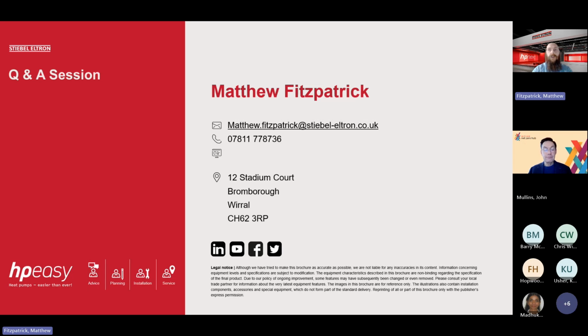So if you've got a gym, a sports arena that needs heating and cooling, and you've got the area, I would say go for ground source because that can use the energy from the ground to cool the buffer rather than using the heat pump. So that's offsetting the cooling costs. And then if it's an office that's well insulated, I would have heating and cooling seasonal rather than simultaneous, quite simply because the heat pump will be able to manage those room temperatures efficiently. Yeah, that's fair.